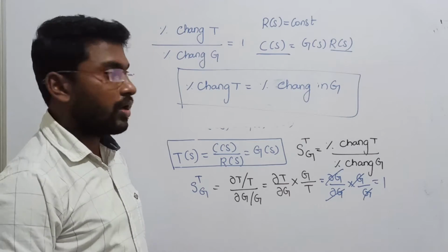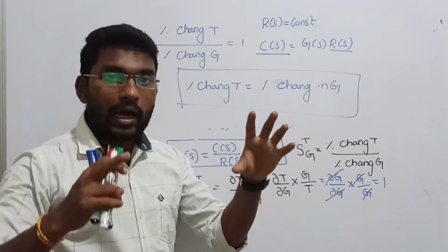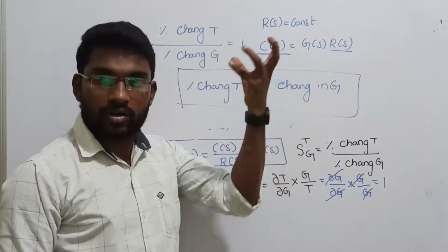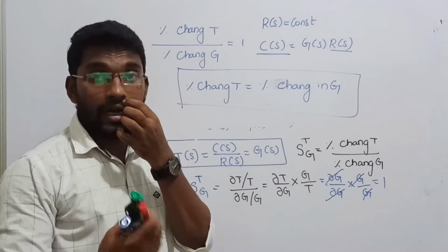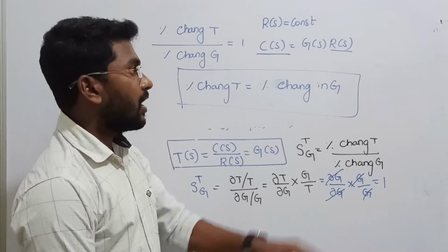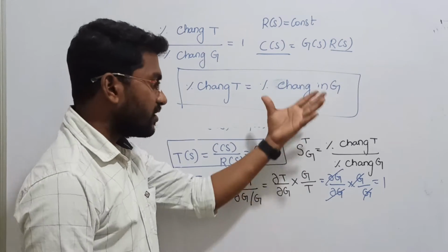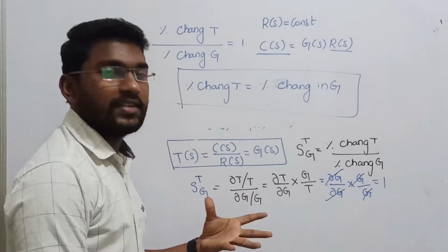What is the actual question they give? There is an open loop system, and suddenly in the system within the block there is a 10% reduction. Then if they ask what change will come in the output, you can observe the same percentage in the output side, because output and the system are directly proportional. Are you getting me? So that is how we are solving, that is how we are testing the sensitivity.